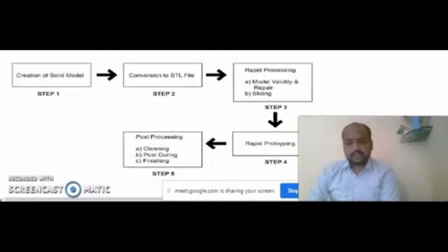See, nowadays 3D printers are used for generating prototypes because complicated shaped parts are very critical to manufacture, and it is very critical to generate their dies required for casting. Therefore 3D printing technology is implemented to generate the patterns required in the casting procedure.